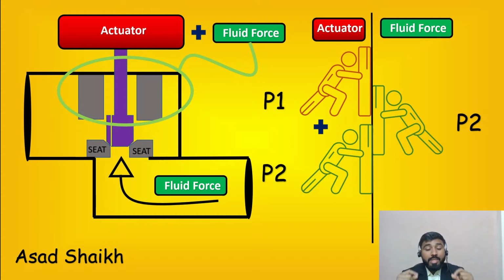So what I mean to say as engineers is, if you see an application requires very tight shut off, try to recommend a control valve for the control application, and for shut off recommend a separate on-off valve as a better choice. In this case, if the client insists, "Oh, I need extremely tight shut off, don't use a balanced trim," question him: how much tight shut off do you need, how critical is the application, will it cause a lot of lives to be lost? If yes, then I think we can easily spend on having another valve to do the shut off application.